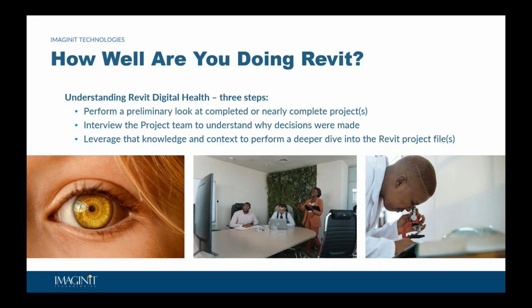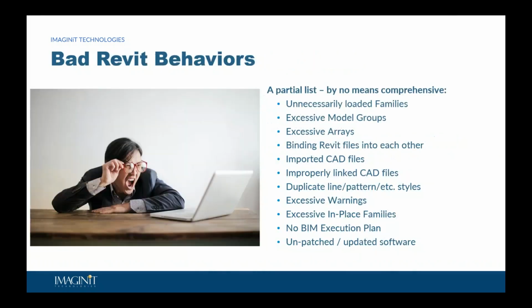Take a look at some of those families, not just looking at how big the family is when you export it out to disk, but what's going on inside the family. Were they made in some of the best ways? Do you have 2D plan graphics and 3D model graphics, or is it a 2D only family? Is it a 3D only family? But do that deeper dive into the project files to come back and identify